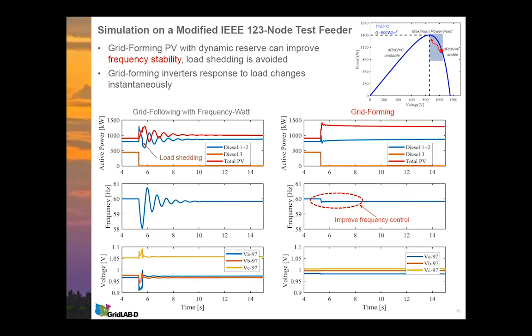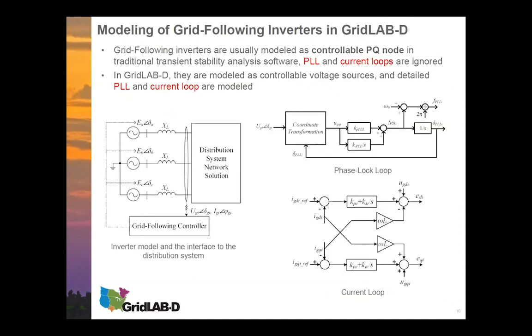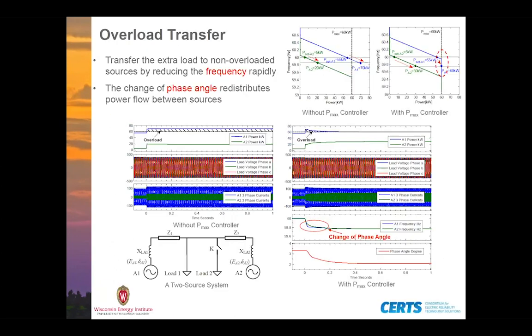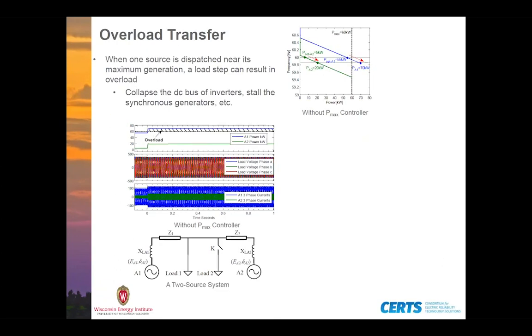So what I'm getting at is very likely what would have happened is that the grid forming converter, because it's a voltage source, and I'm assuming here I may be wrong, you didn't have a direct limit on the current being injected, it injected as much current as the network required, right? And that's why you have a good voltage response. The moment you limit that current injection from the grid forming converter, the voltage will drop. Yes, at a certain level, I believe you need to worry about your currents.